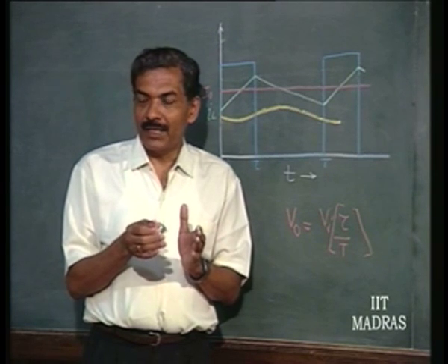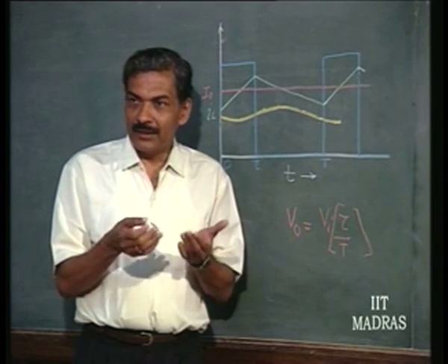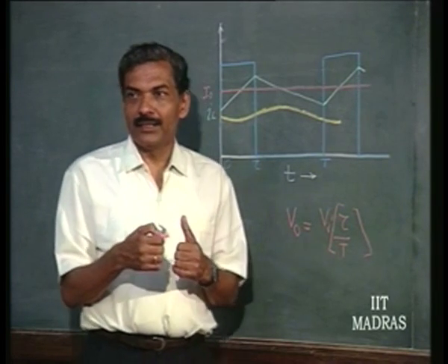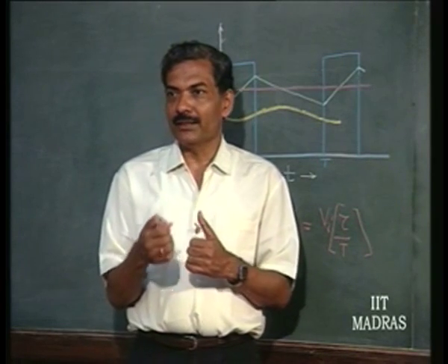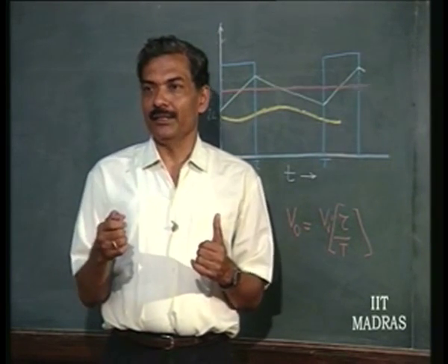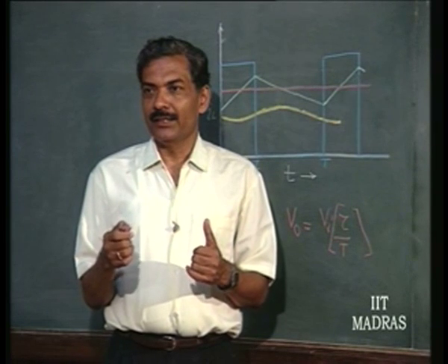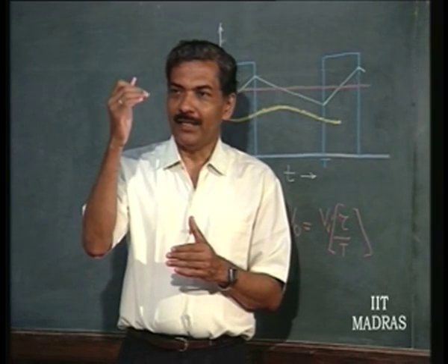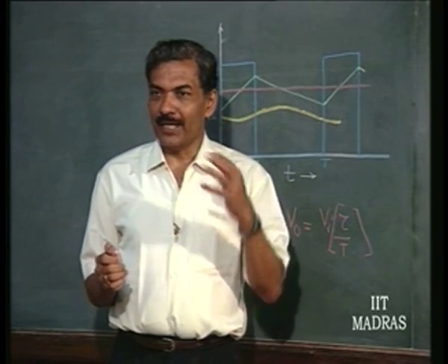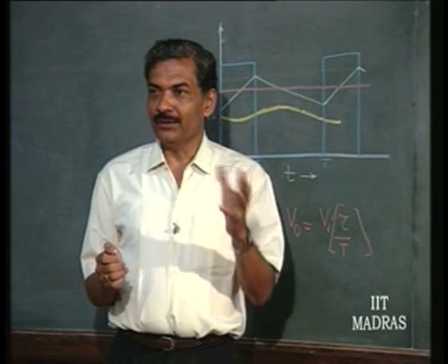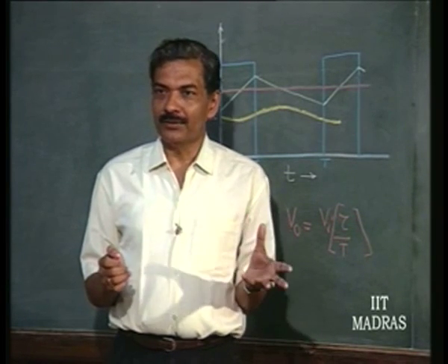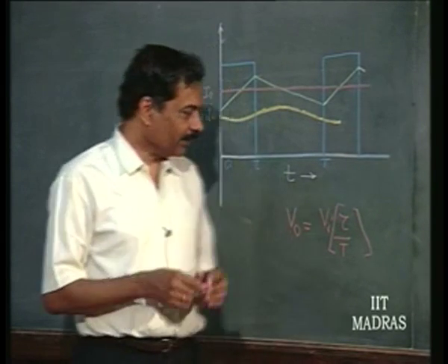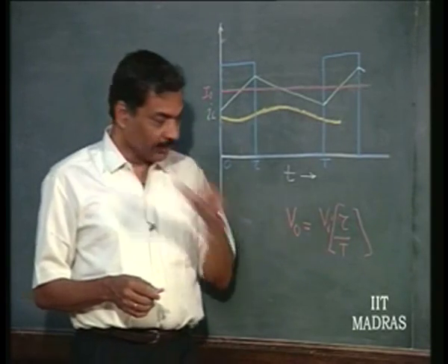That is done by giving what is called regenerative positive feedback to the comparator, and the comparator is nothing but a Schmitt trigger. So, it makes sure that it always operates either in high or low, so as to drive the transistor switch either to off state or to completely on state or saturation state.